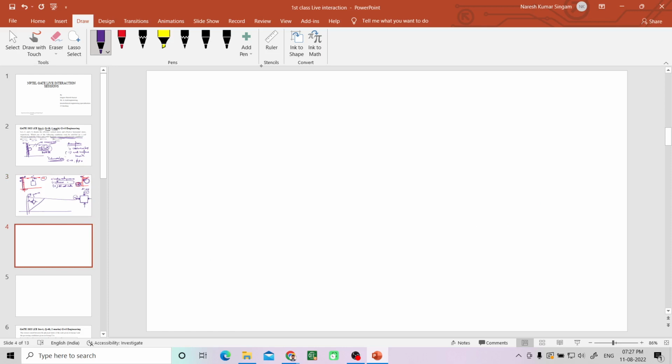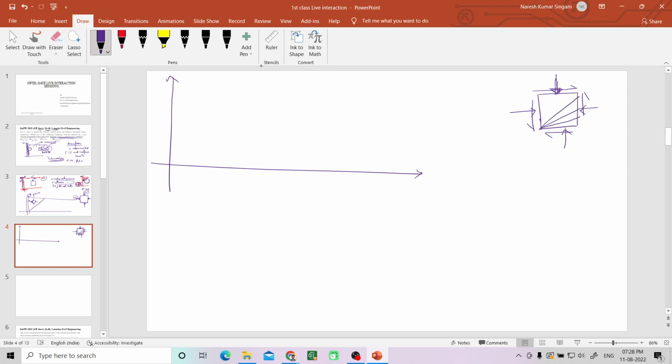So let me explain briefly what is the Mohr circle and what it defines. You take any soil element and apply any kind of pressure, any kind of loading. There may be some shear stress along this plane, or there may not be any shear stress along this plane. Anyway, when you apply any kind of loading onto the soil element, there are an infinite number of planes existing in this soil element, right? This is also a plane, horizontal plane, vertical plane, horizontal plane, again vertical plane, this is inclined at some degrees. There are infinite number of planes.